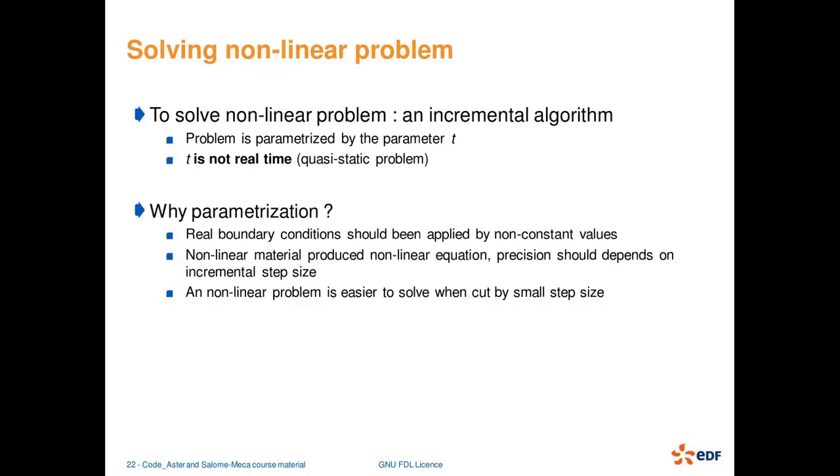Similarly, a nonlinear material produces a nonlinear stress-strain curve, and therefore based on the deformation I need to find out the strain and the corresponding stresses from that nonlinear relationship, and therefore the precision of my solution will depend on those increment sizes.